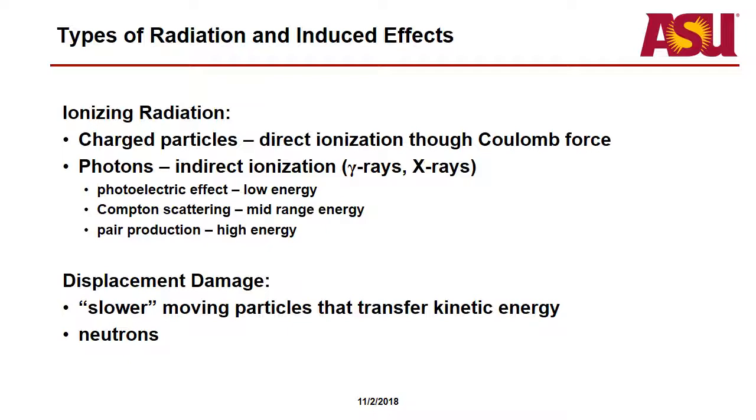Essentially the particles will slam into an atom, and that atom in the material can either absorb some of the energy and stay in place, so you'll have a transfer to phonons, or that atom absorbs enough energy to be ejected out of its placement in the material, and then it scatters elsewhere. It now has kinetic energy and can cause a cascade of damage throughout the material, in addition to whatever energy your initial ion has as well, because it can continue to go on and create an additional damage path.